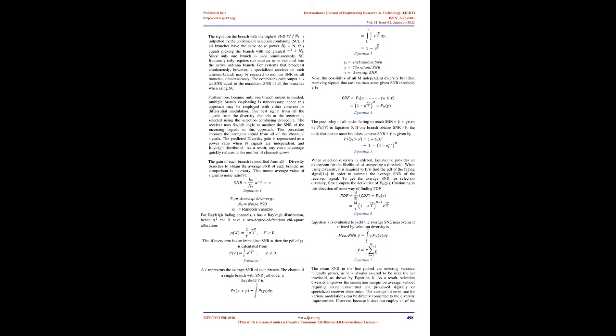When time variation is more important, as with channel coherence time, diversity is done by sending the same signal at different times. Increased temporal diversity does not necessitate more power, but it does limit data rate, because data is repeated in the time slot rather than new data being sent in that time slot. We focus on space diversity, while the principles can be extended to any diversity. Receiver diversity is considered because its system models and combining processes are fundamentally different.